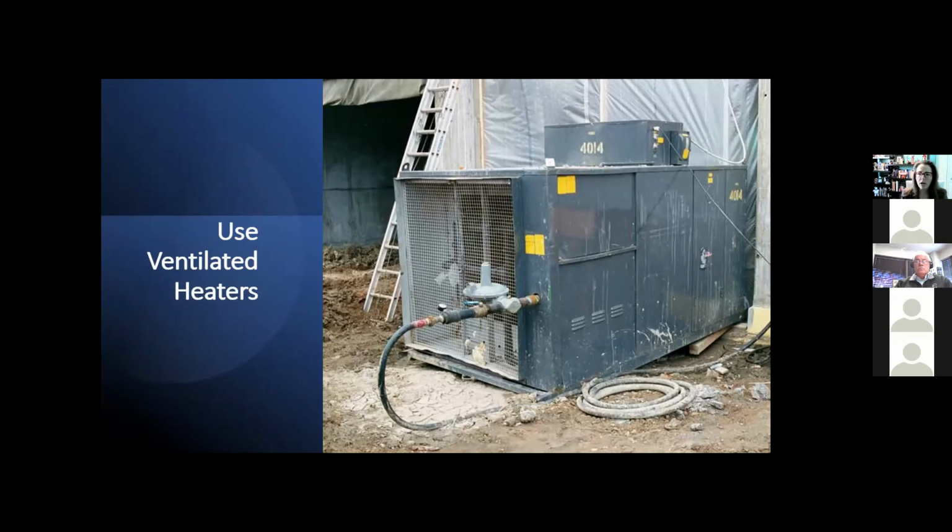So for instance, on a small project where you might be driving the worker truck up to the edge to take the equipment out, and you might leave the truck on. If that exhaust from the truck hits the surface of fresh concrete, it can cause dusting. So that's another example. If you ever get dusting in certain areas and not in others, it could be due to irregular bleed as well. So if you have a high amount of bleed in concrete, that excess water comes to the surface and then you work it into the surface, that can also cause dusting.